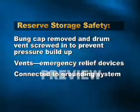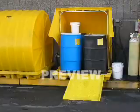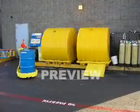Proper vents also incorporate emergency relief devices, which blow out under extreme pressure. Drums also should be connected to a grounding system. This eliminates static electrical buildup when dispensing from the drum. If your plant does not have a drum storage room, drums should be stored in a safety cabinet. They are available in sizes to hold drums vertically and horizontally.